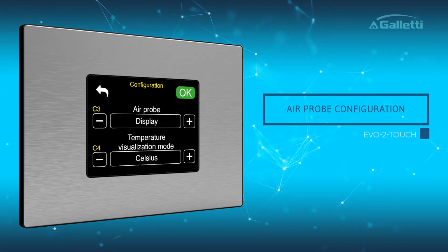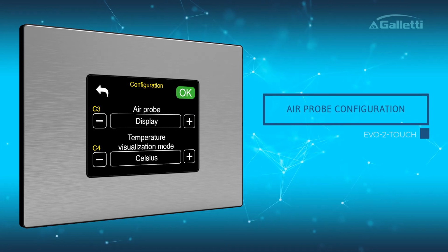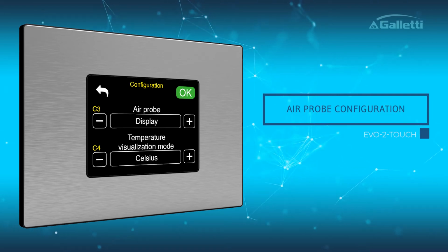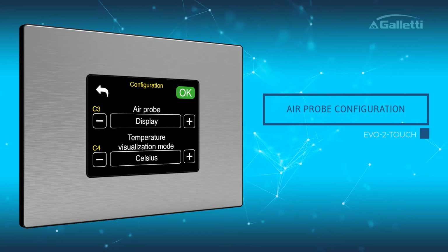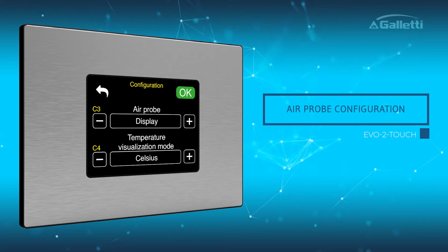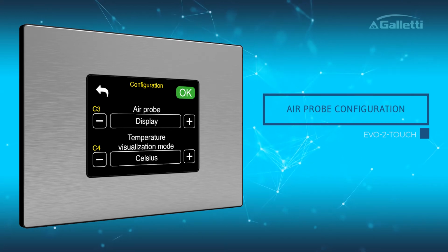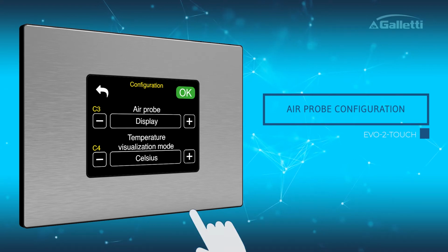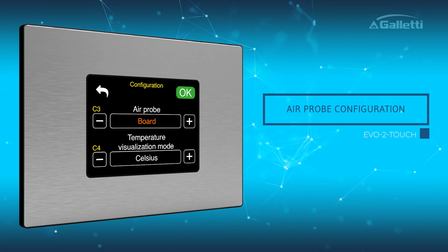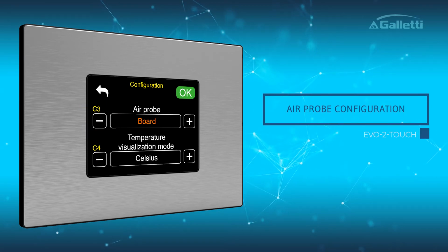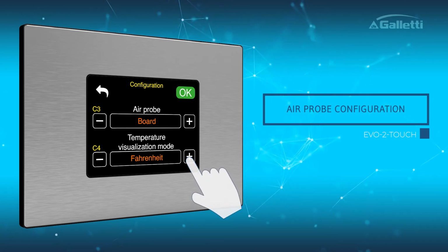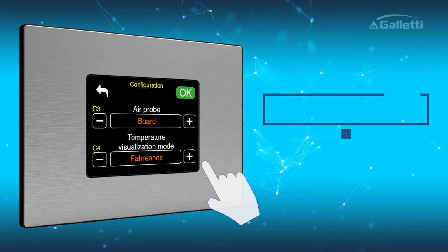In particular, the next screen is used to configure the air sensor. It is, in fact, possible to use a remote air sensor to regulate the room temperature. If used, it becomes the main regulation sensor in place of the sensor located in the user interface. Therefore, to choose which sensor to use for regulation, press the plus and minus keys in field C3. In field C4, it is also possible to set the unit of measurement to be used, Celsius or Fahrenheit.